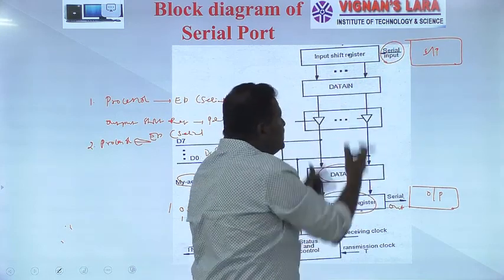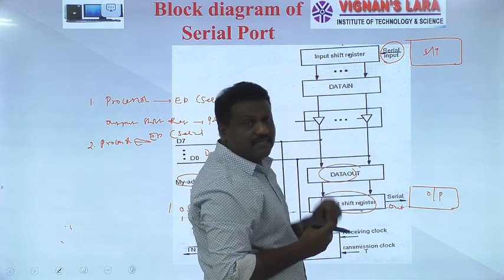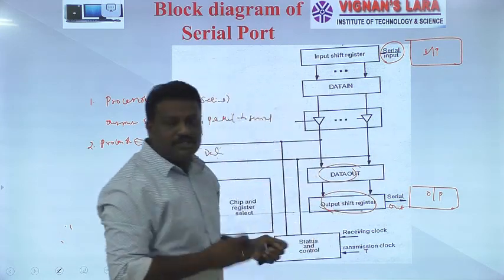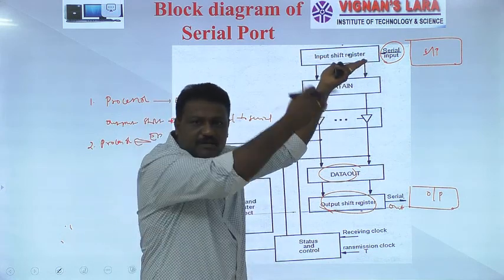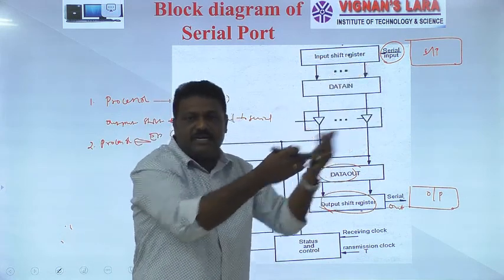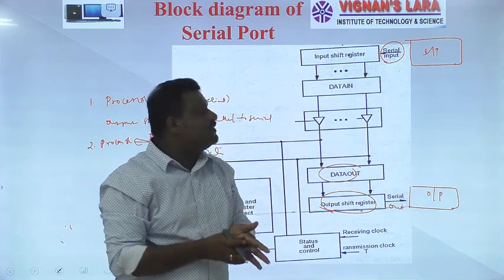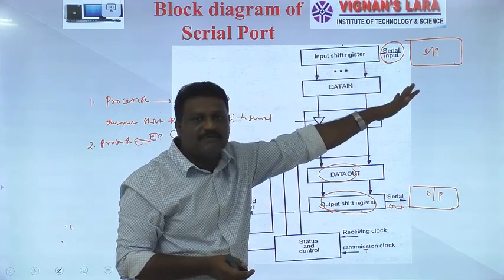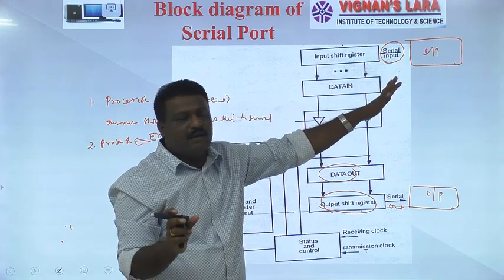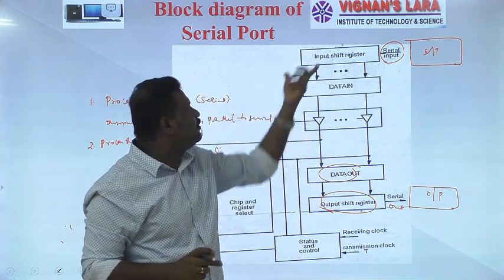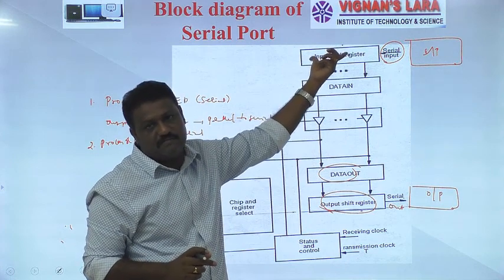It means your I/O interface collects data bit by bit from an input device. The data is copied onto the input shift register. Once it receives all the bits from an input device, for example, I collect the data in terms of bytes. That means if I successfully receive 8 bits from an input device, that is one frame or data byte. Later that byte is converted into parallel form by this input shift register.